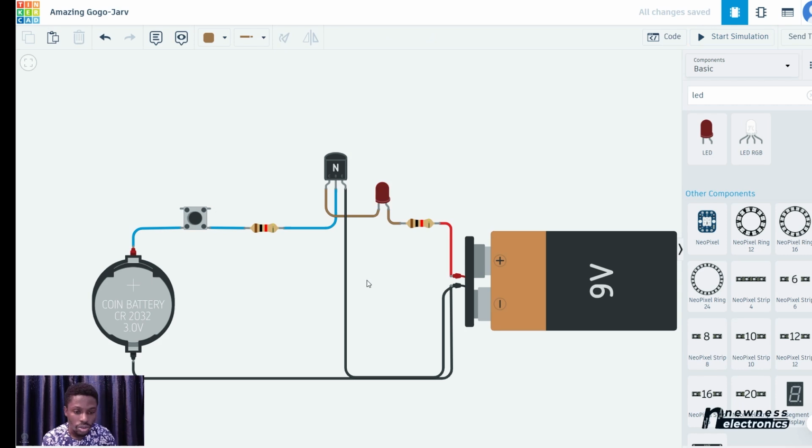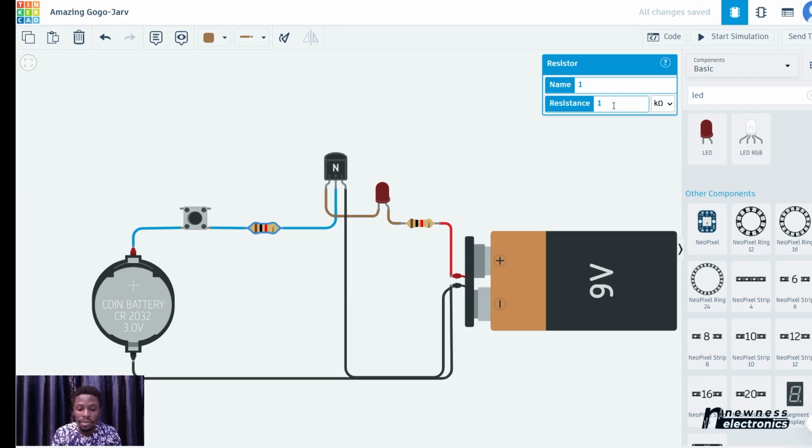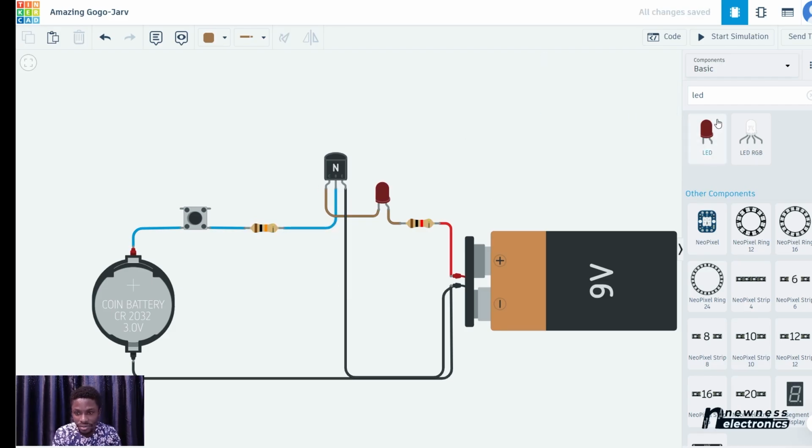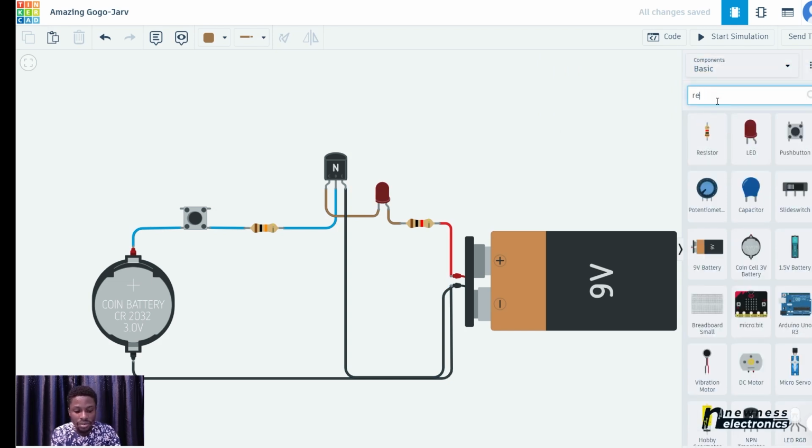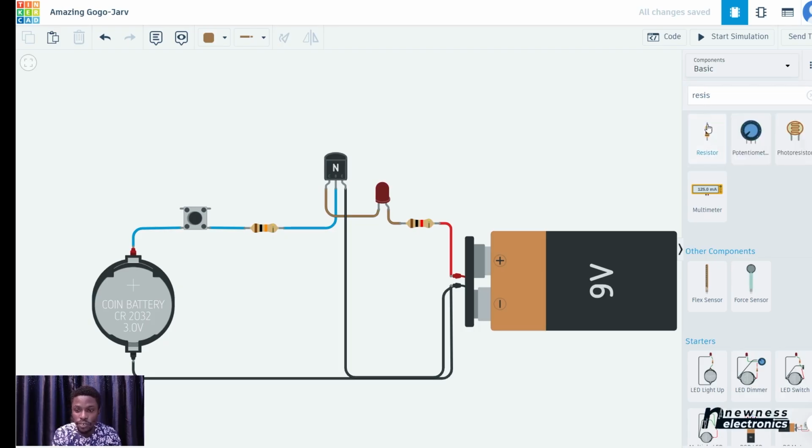Alright, I will tell you why it's on. In transistors, because of the sensitivity, the little amount of current it needs to turn on, if you leave the base line floating, sometimes it can get electricity from neighboring static electricity. It can misbehave, it can be on. And most times, if you leave it floating, it's always on. So first, let's set the proper value for this. Remember I said 10K is good. You attach a large resistance to the base that pulls it to ground. This is a very important step, or else you will not have the result that you want for your transistor.